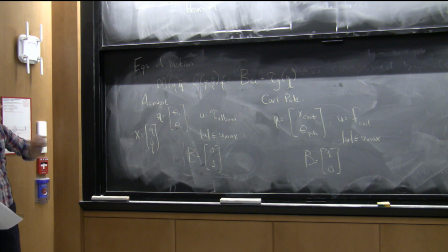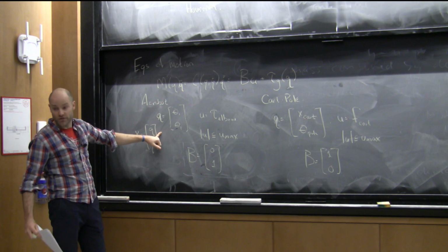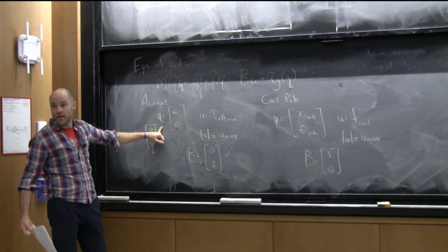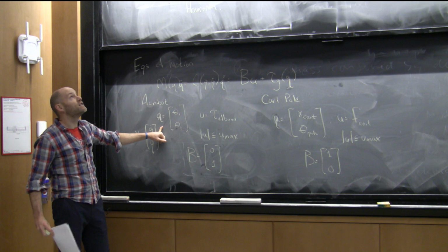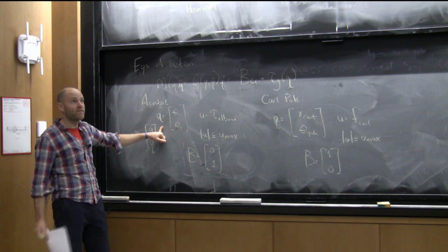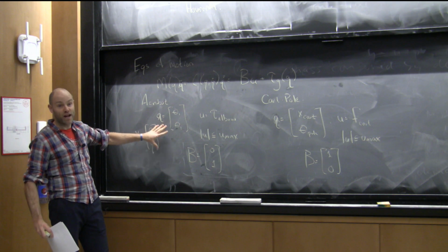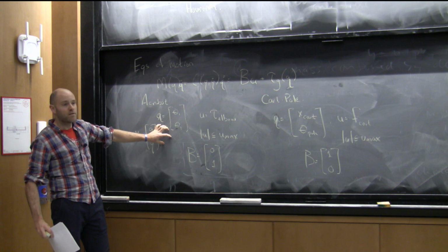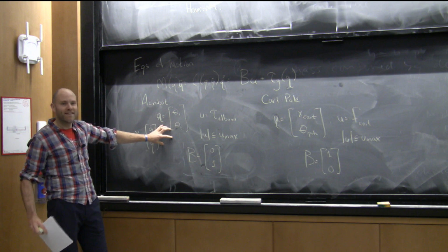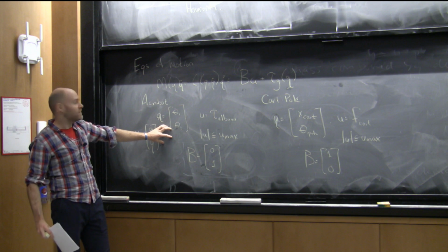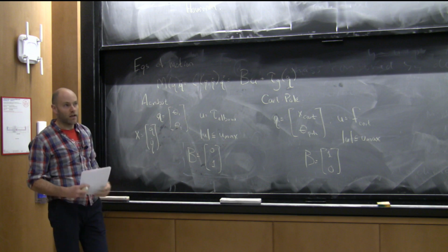Okay, so we have the tools from dynamic programming at our disposal so far. I now have a 4-dimensional state space, you're right. Could I build a mesh over the 4-dimensional state space and use exactly the same tools that I showed on the pendulum? Sure. You'll run value iteration and you'll get a controller out. And then my guess is that you'll run that controller and it'll fail to get to the top, for the Acrobot at least. Then you should proceed by saying, what if I added more resolution to my mesh up by the upright? You'll run your value iteration for longer, because suddenly there are a lot more bins, and it'll almost get to the top, and then still fail. That's a procedure you can continue if you're patient, and I think you would succeed.